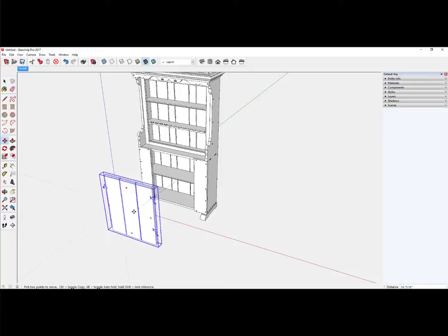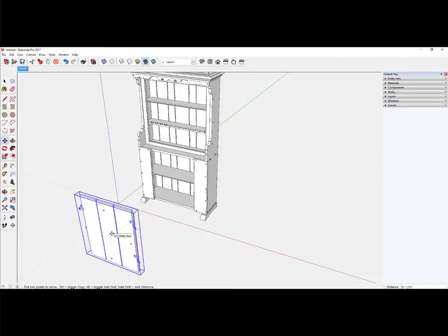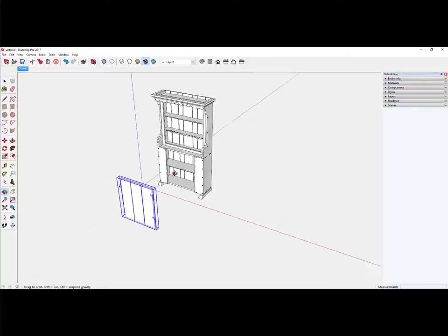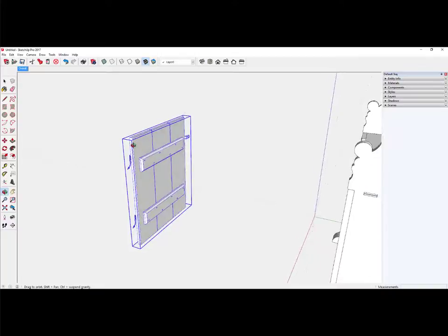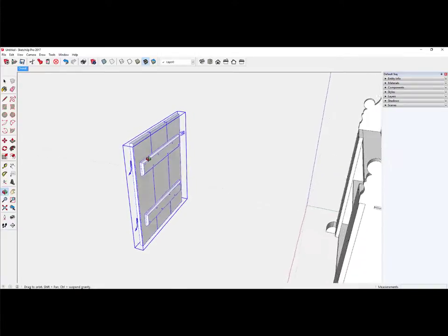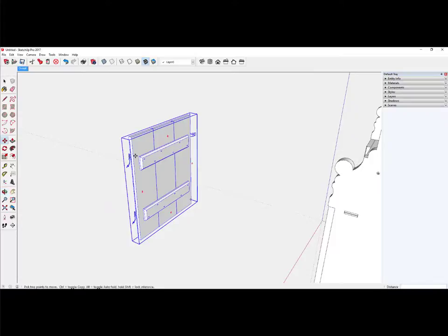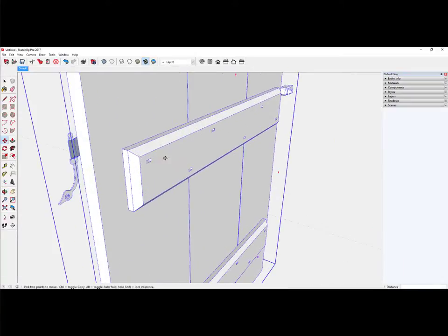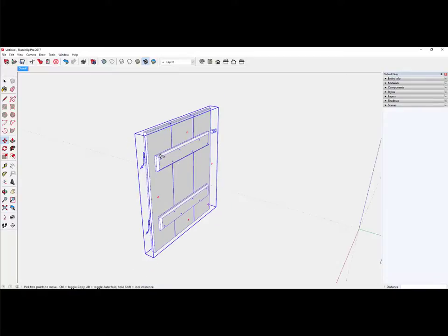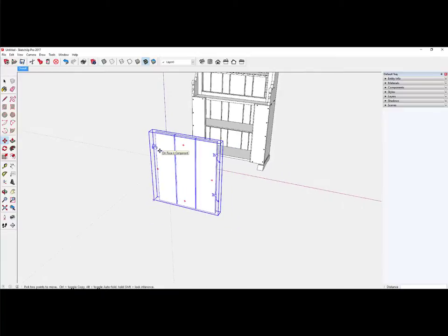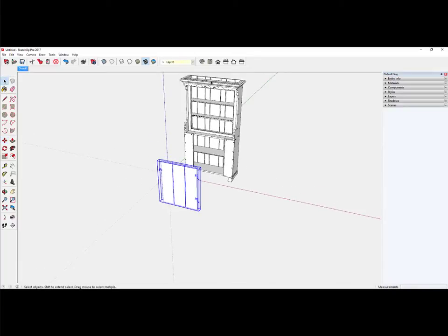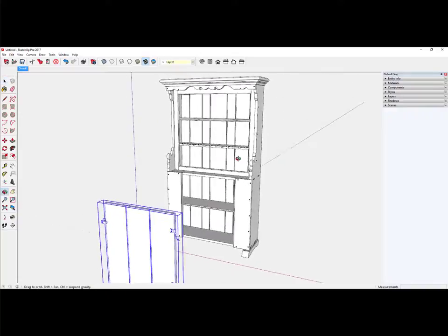I'm doing that in the shop right now with the Monterey pine. I'll pull the door out of the assembly, and you can see that it is also a batten door. It has two horizontal battens that accommodate wood movement. They're little slots for the screws, and nothing will be glued here. It needs to allow for movement of the wood cross grain. Now, how would I go about making this door component?